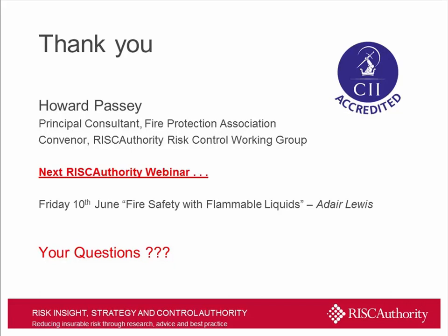As you've said in your question, I've seen a number of cases where there's been extensive overprinting and advertising, and there is a need to ensure that whatever's being done isn't going to impact on the ignition propensity of the materials themselves and their potential for fire propagation. But quite where you'd go for that, I'm not entirely sure. I'm sure this is a question that BRE must have been asked, so it might be worth asking them to see if they know. I see from your question you've asked for them to be removed in the past, and for want of a better answer, that's probably the best way forward.